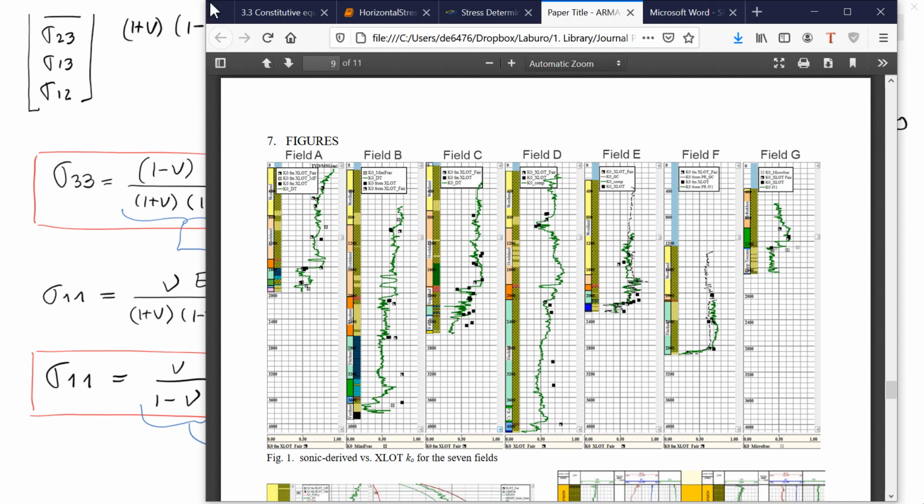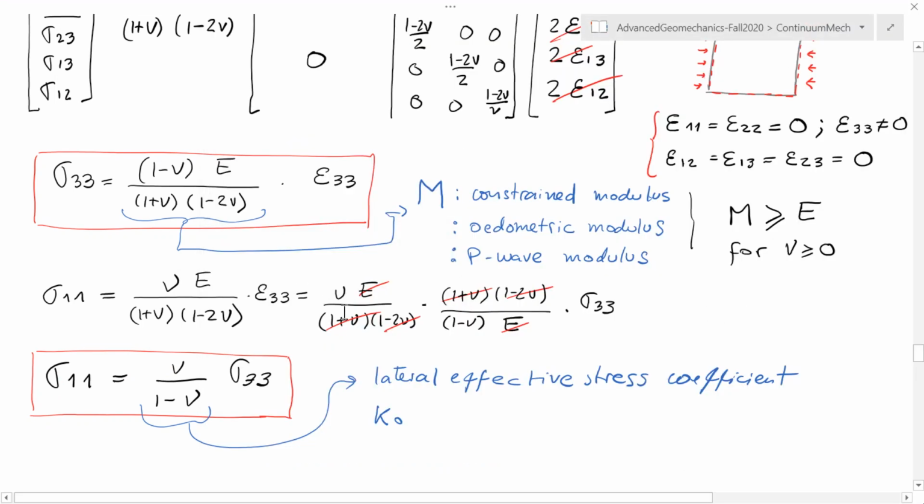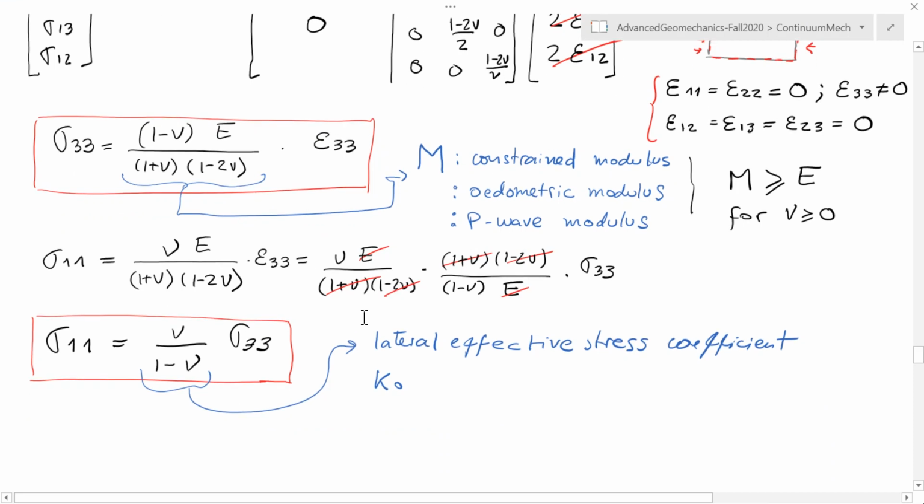As we saw before, we can calculate an effective Poisson ratio, even though some materials are not linear elastic, that allows us to utilize this equation to predict horizontal stress. But we're also going to see other properties of the materials that can help us determine this horizontal stress a little better, taking into account more complex processes that happen in the subsurface.